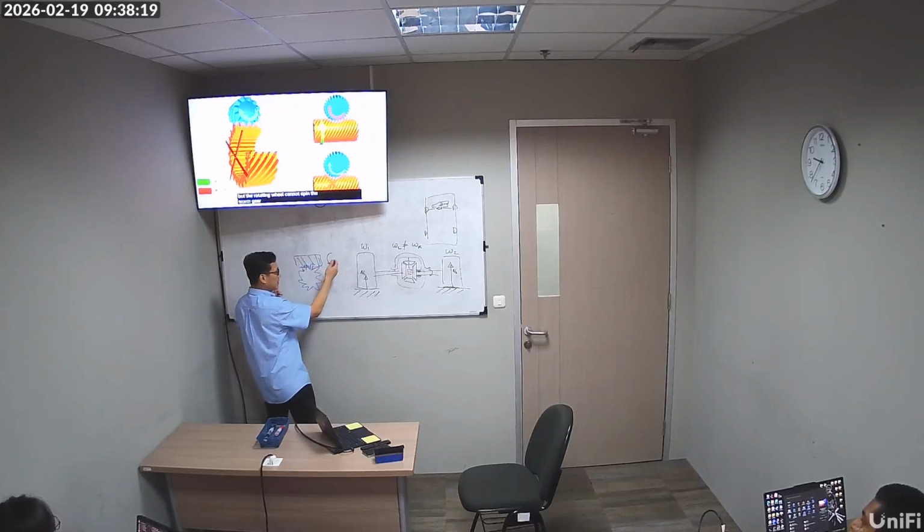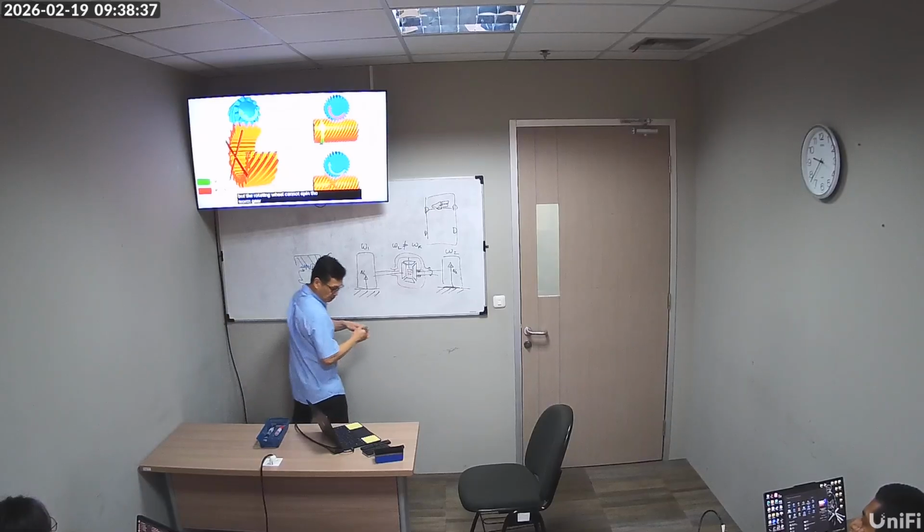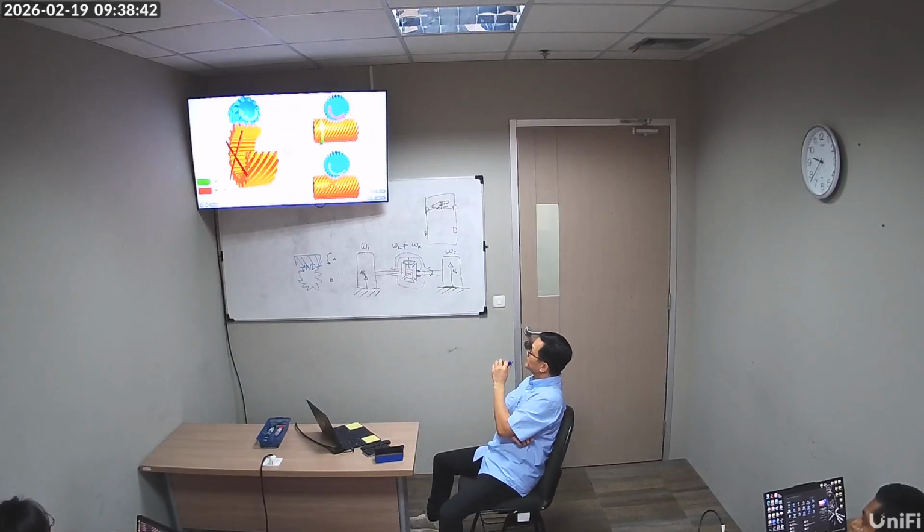But the more extreme the ratio, the more not back drivable it is, right? So, this will basically just halt. So, this A can drive B, B cannot drive A. Throughout this discussion, just keep this principle in mind.